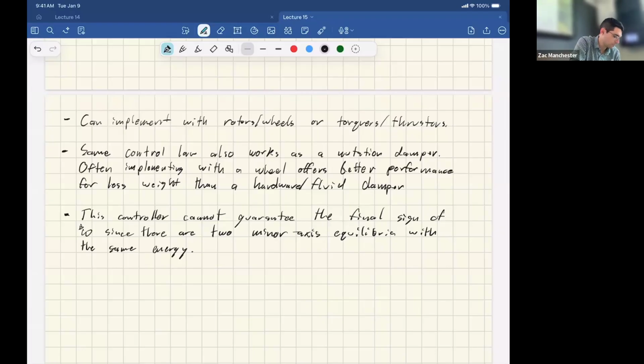So typically, ultimately I control the torque on these things, or some things have built-in controllers, so you do velocity control. But if I'm commanding torque, I have the same Jacobian that maps applied torque on the wheels into total torque.